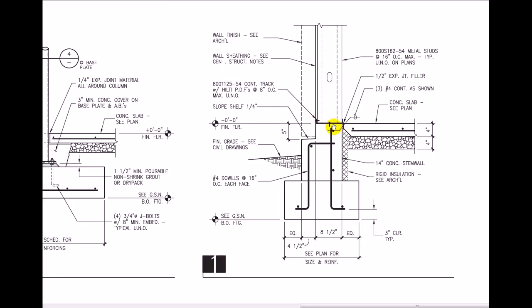and then the specifications and notes will tell how to fasten them together. On structural concrete drawings, these heavy lines indicate rebar. The size of the hooks are usually not shown because those are standard per ACI specs. So a standard 90-degree hook is what the contractor would give there unless there's a dimension shown. A circle indicates a rebar that we're cutting through, so those are longitudinal ones. So you can see in this wall, you can see this line here.